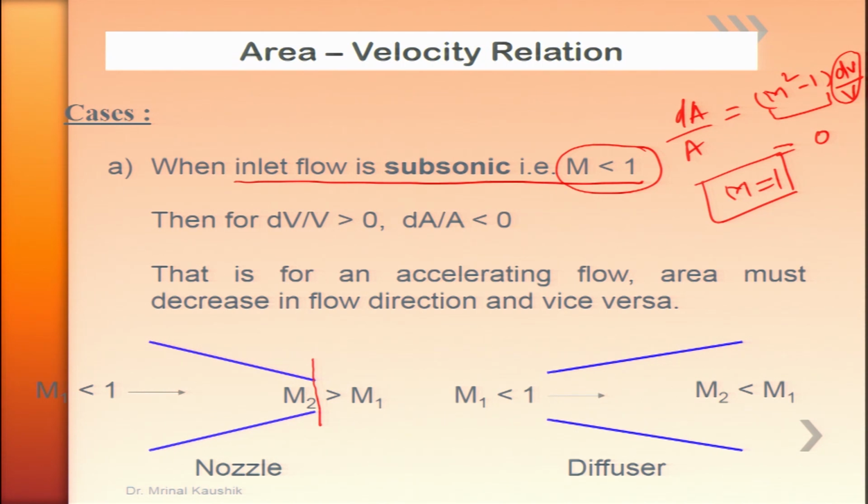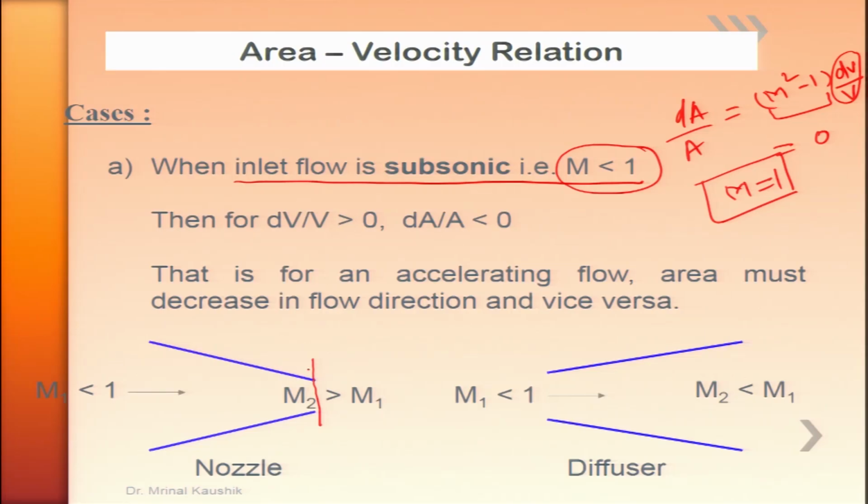Therefore, if you want to achieve a supersonic flow at the exit, you can clearly observe that soon after the exit of a converging nozzle, I must diverge the passage, so that for the subsonic case this becomes a nozzle, and for the supersonic case this becomes a nozzle. Hence this duct, to obtain supersonic flow at the exit, is called a convergent divergent nozzle.